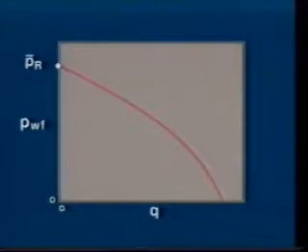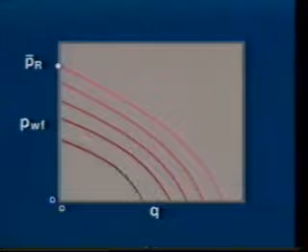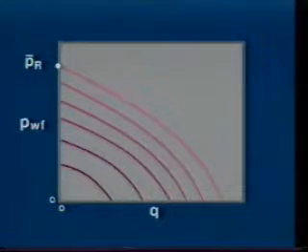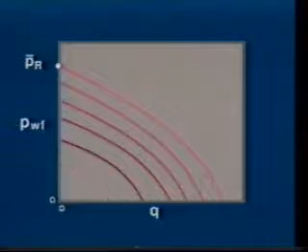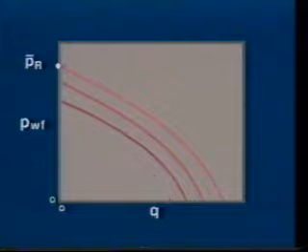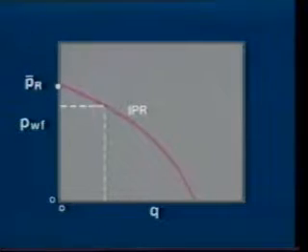Because the reservoir pressure usually decreases as more fluids are produced, the IPR over the life of a well will shrink toward the origin. This family of curves then shows how a well's potential to produce at any given bottom hole pressure decreases with declining reservoir pressure. Note that if the flowing bottom hole pressure is held constant as the average reservoir pressure drops, a well's production rate will decrease until it no longer flows.